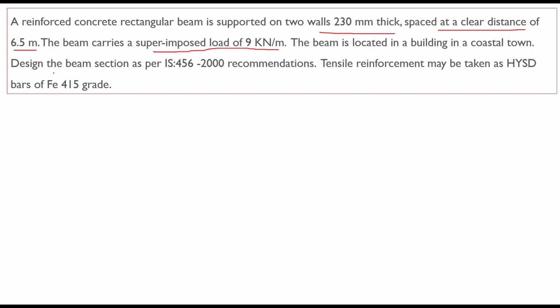And what we have to do is design the beam section as per IS 456 2000 recommendation. And regarding tensile reinforcement, it is mentioned that tensile reinforcement may be taken as HYSD bars of Fe 415 grade.